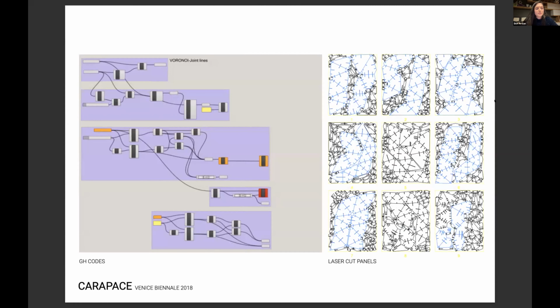It is easy to fabricate the units because plywood is a material that can be cut by laser cutter. The whole macroform can be cut in a maximum of 2 days. These are our laser cut panels, 9 of them. After the laser cut of the units, it is easy to transport them. Due to its parametric design, it is possible to adapt the interlocking system of the macroform.